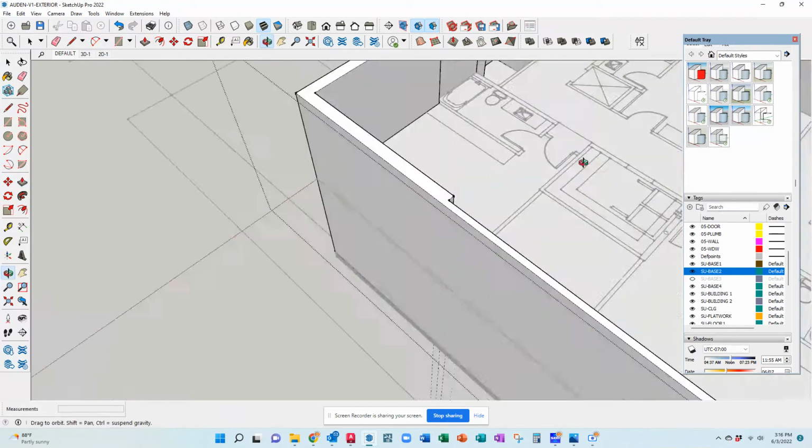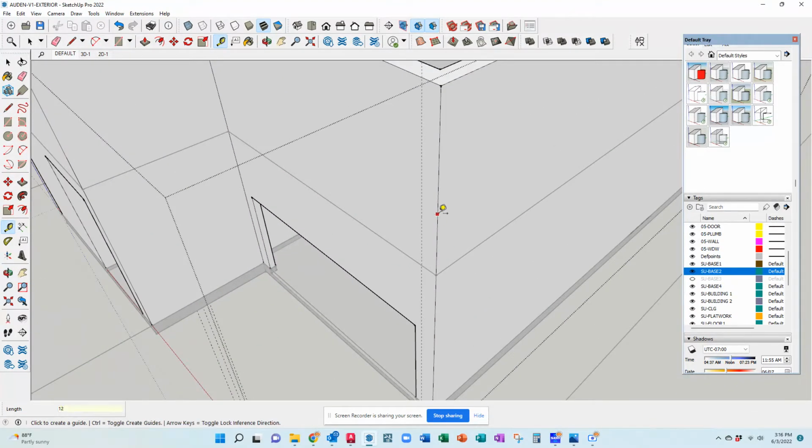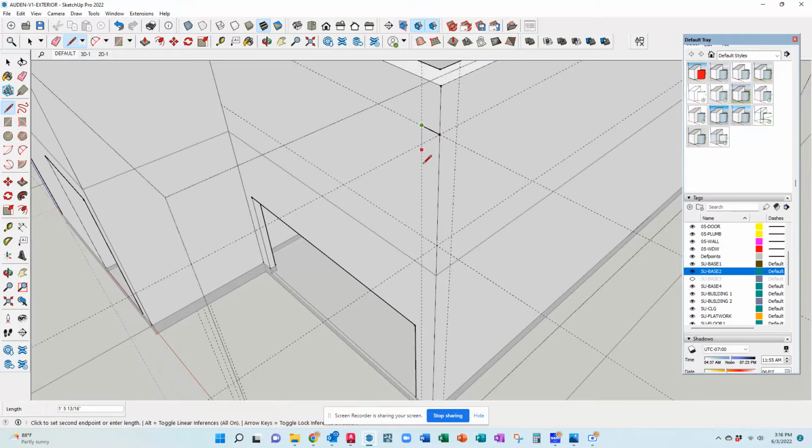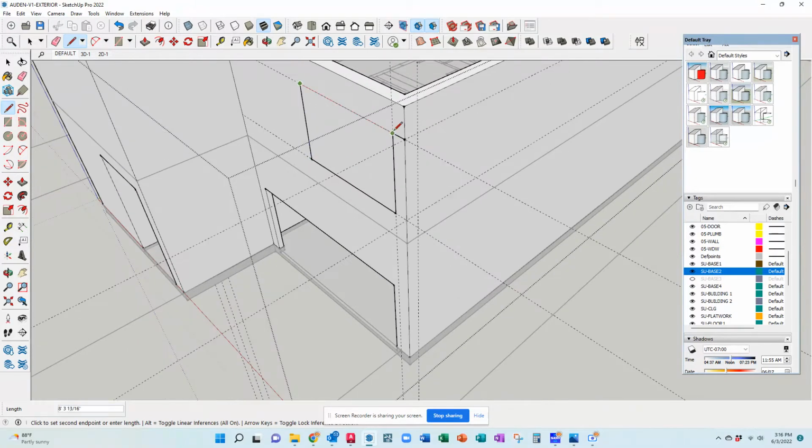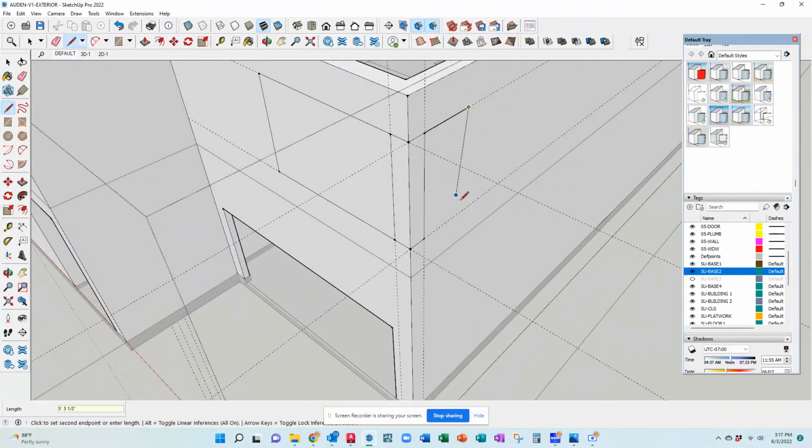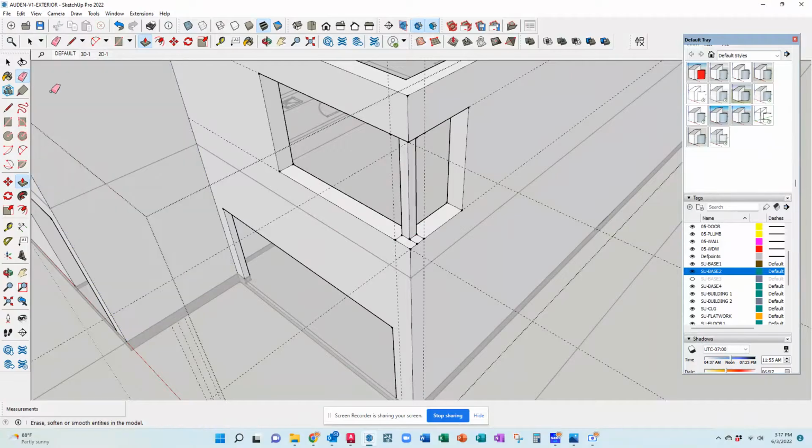Here I'm thickening some walls. We'll do some double frame 2x6 walls here to give a total depth of 12 inches. That way the window assembly can actually be recessed back in the wall from the exterior. Gives us just extra depth, some shadow line interest, which you'll see later on here in the model as we develop things.